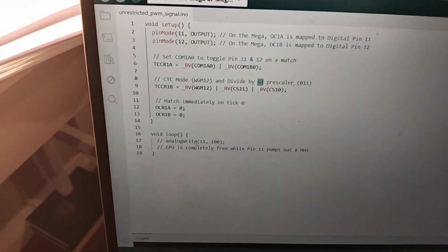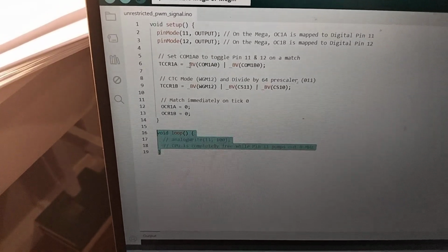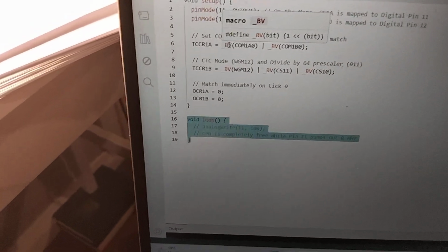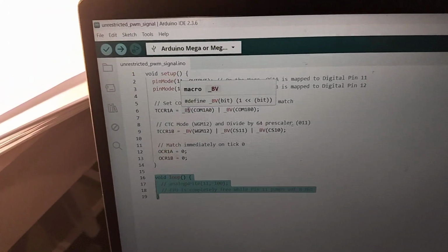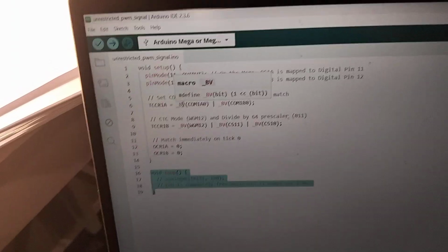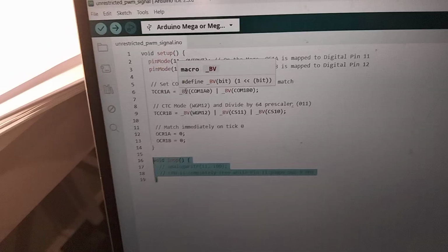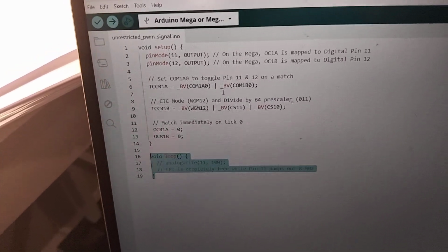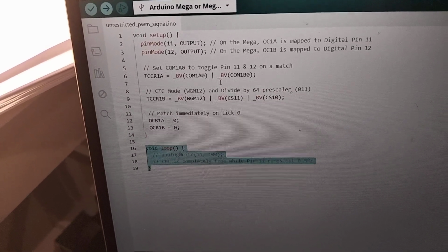And you can see that there's actually no code run in the loop because everything is just set in setup, and it actually doesn't use the CPU. The Atmel Mega 2560 chip has all these hardwired instructions that check certain registers, which on an MCU is actually just a block in memory. So it checks all these register values and automatically triggers hard-coded instructions to flip the pin on and off. And yeah, so that's it.